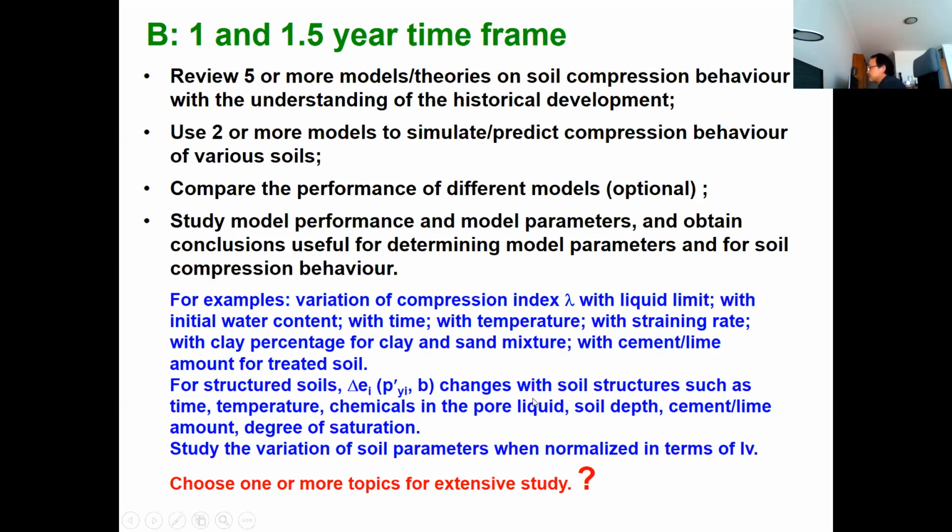For example, some people studied how the compression index lambda changes with the liquid limit. They found that the higher the liquid limit, the larger the lambda value. Or someone studies lambda with water content. And some people even study lambda with temperature. So you find how much is lambda in the winter, and how much is lambda in the summer.